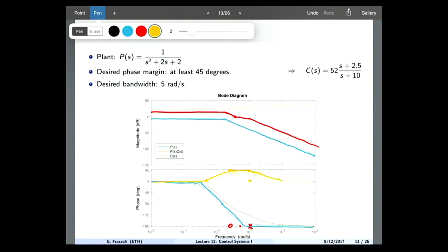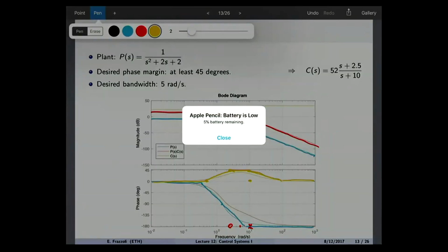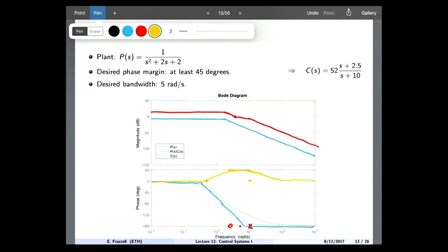As you see, here you can get a sense of how much your phase will increase, depending on how close the two are. You can get a sense of this just by sketching that Bode phase plot. By sketching it, you actually do get a good sense even with a simple sketch.